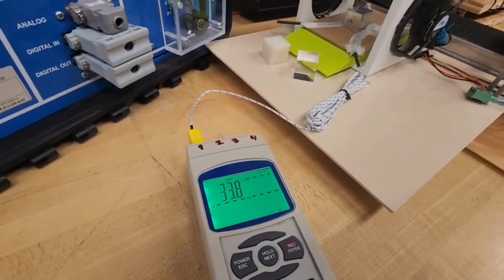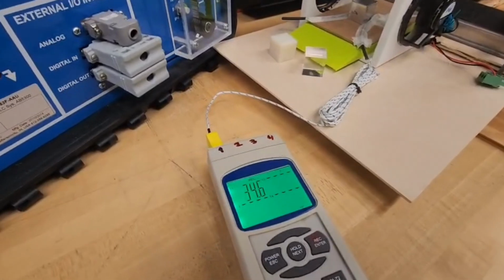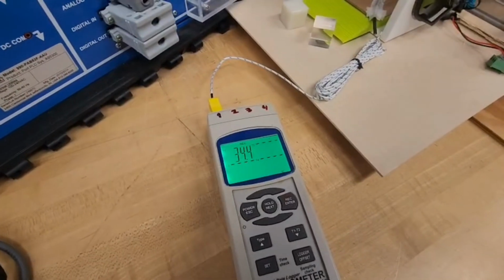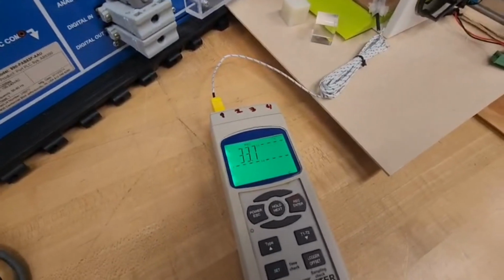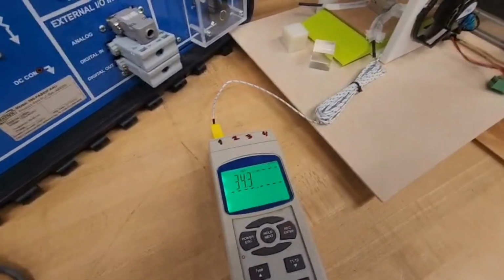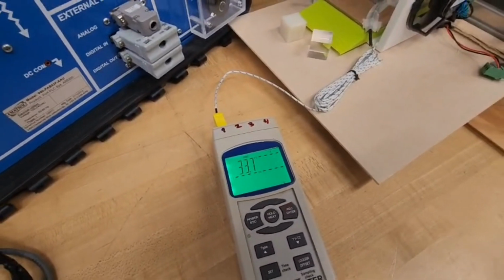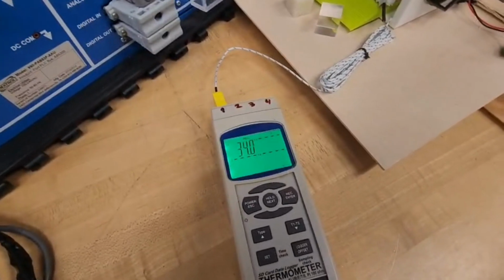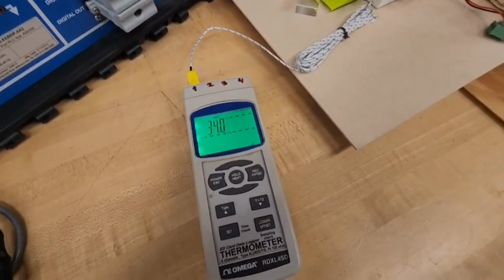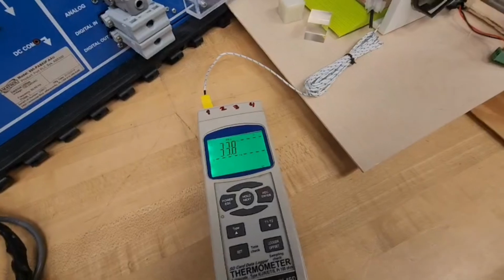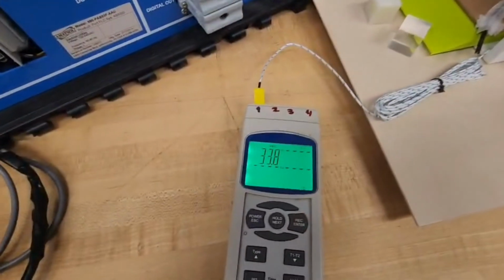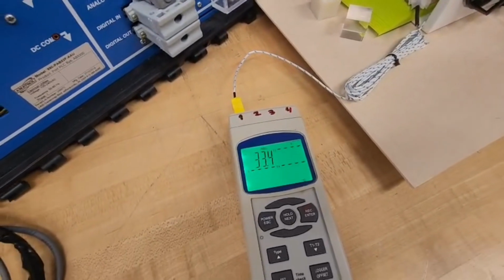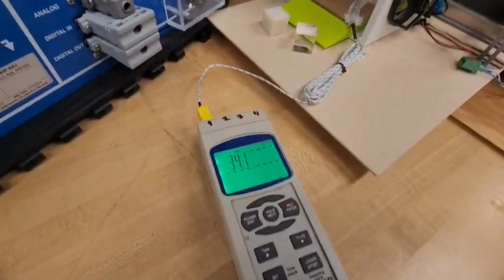Now, as I told you, we have started the low cooling schedule, so we can see the results. We will be getting a low cooling drop, and just like this, if we set it on a 50% duty cycle, we will get a comparatively faster cooling rate, and if we set it on the high cooling rate, then we will get a faster drop in the temperature. So this is just an example of how we can play with the timers' timing, the on and off of the fans, and manipulate the temperature drop rate for different components or different materials, because temperature drop really matters with the properties of the component.